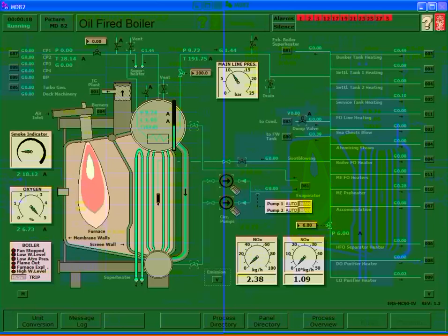They're the least efficient. Yet, because it has a 1,400-pound boiler, and instead of a burner, I'm using a gas turbine now. And I'm burning that fuel, and I'm putting it into that waste heat boiler. And then that steam produced on the waste heat boiler is running a generator. So you're jumping from 35% efficiency to 60% efficiency, and 60% plant efficiency is about as good as you get in our world. So because it's combined cycle, I can run that gas turbine and have high efficiency.